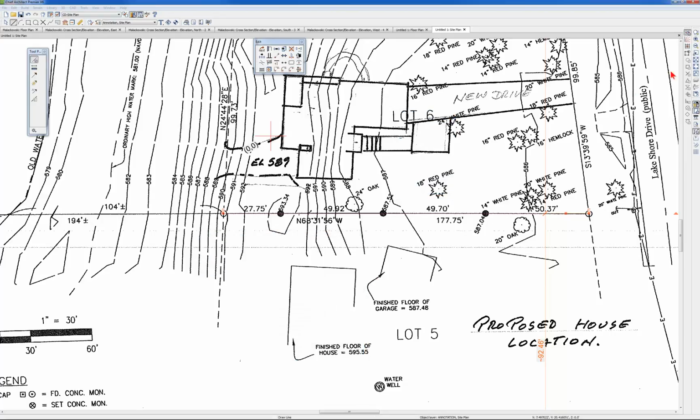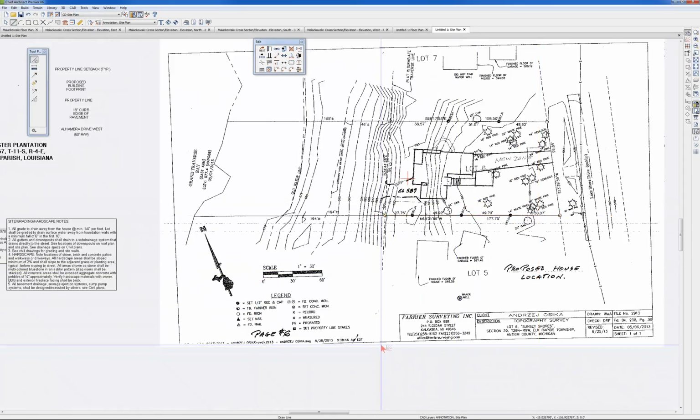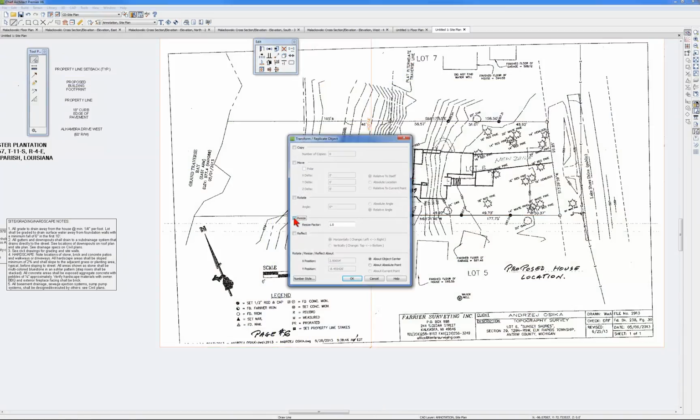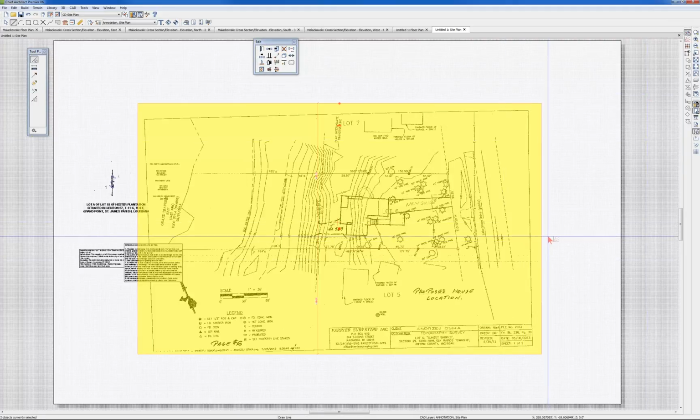and say okay. All right, now I go back out. I keep that line selected, and then I pick the PDF. And I go up here to resize, and I'm going to resize the whole thing by that number I just wrote down, 1.50635593220339. Okay, if that ain't close enough, you'll need to find another job. Okay, so there it is.